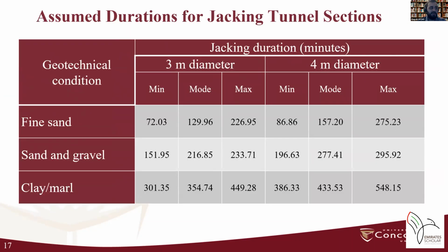Because of the difference between the dimensions of the assumed tunnel and those of the tunnels in reviewed projects, the jacking duration was modified according to the diameter and length of the sections. As an example, we can see in this table that in a 3 meter diameter tunnel in fine sand, the jacking duration is about 72 minutes.